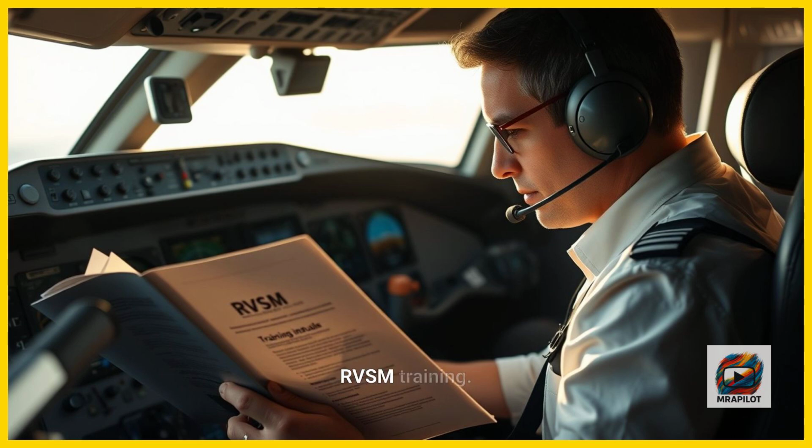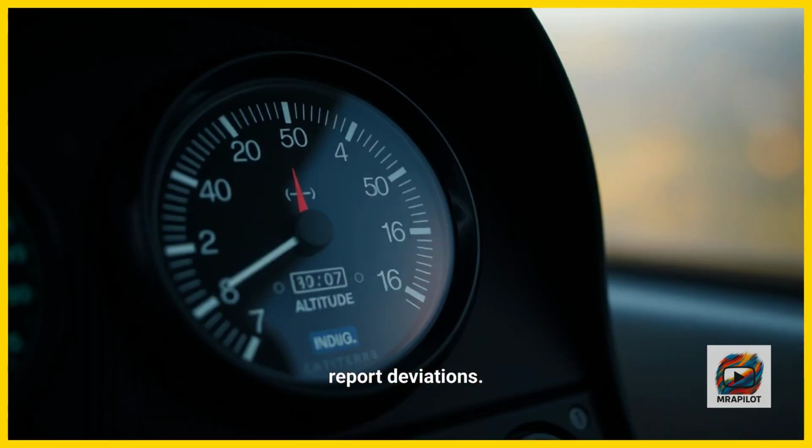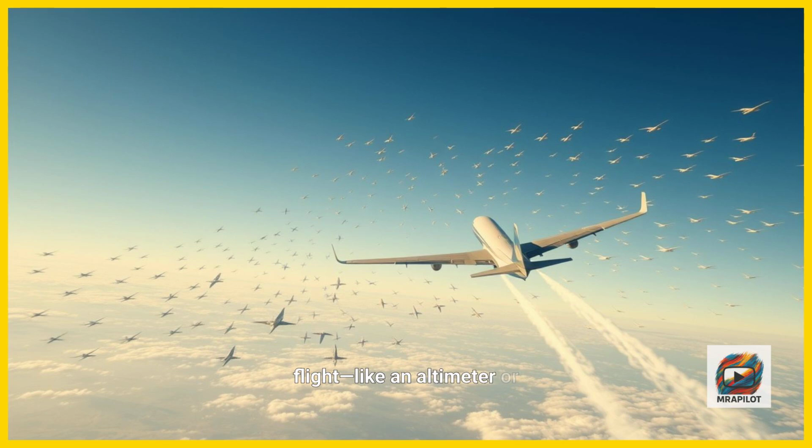Pilots also need RVSM training. This includes understanding altitude monitoring procedures, how to detect altimeter discrepancies, and how to report deviations. If anything fails in flight, like an altimeter or autopilot, you must exit RVSM airspace as soon as possible.